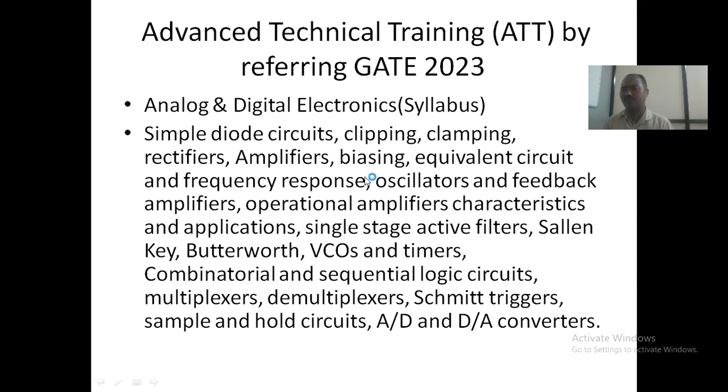But in case of a full bridge rectifier, a bridge of 4 diodes is used, so that at a time 2 diodes work. That's why the noise in case of your full bridge type rectifier is less than that of your full center tap type of rectifier. That's why the full bridge type configuration is used more in industrial as well as day-to-day applications. That is the reason behind it.